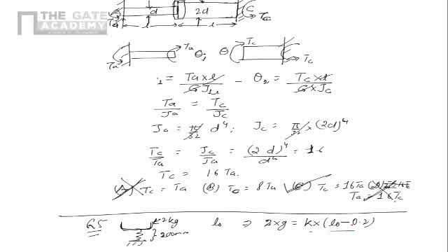Now when a mass of 20 kg is placed on the pan, the length of the spring becomes 100 millimeter. So when 20 kg is placed, the total mass is 22. So 22 multiplied by g is k into L0 minus 0.1. So that's the second relationship.